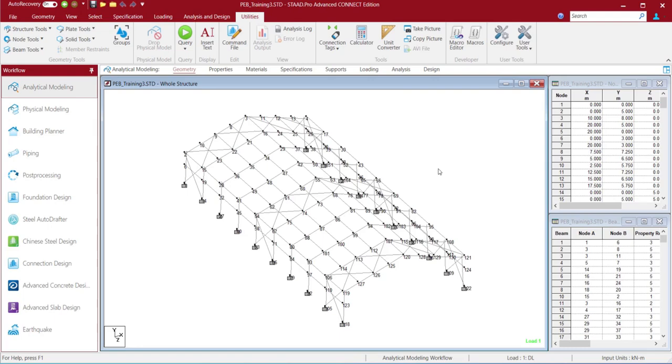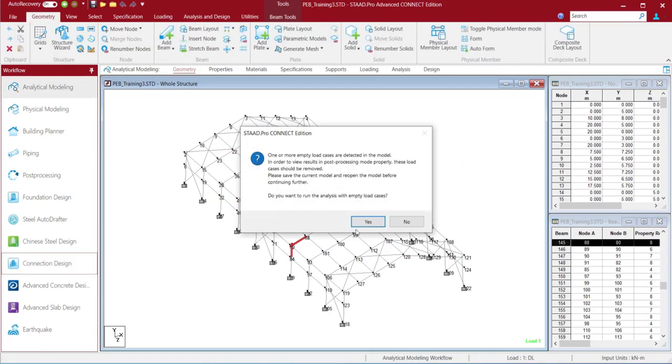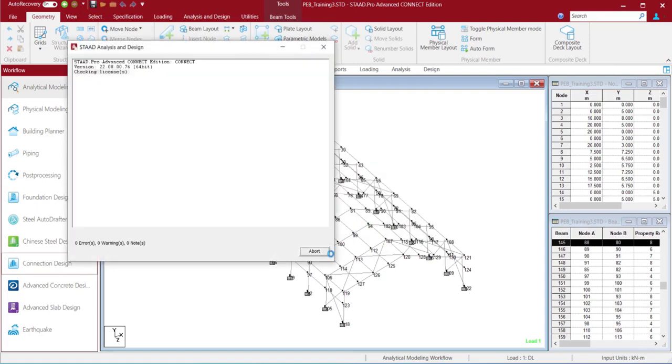It will search for all the design rules suitable for the BCF. Now, as this is a PEB structure and my beam slope is more than 15 degrees, I have to assign this attribute definition to that beam. Okay, now this time it should probably work. Now let's select these two joints, and I must rerun the analysis.